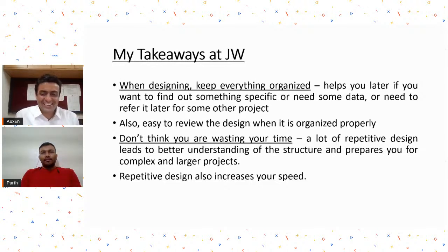It helps you a lot when it comes to larger and complex projects, because if, let's say, you have done 600 beams daily for 15 days, you have done a lot of beams to know what type of behavior could be expected when it comes to, let's say, shear wall to shear wall beam, or shear wall to column beam, or a secondary beam.